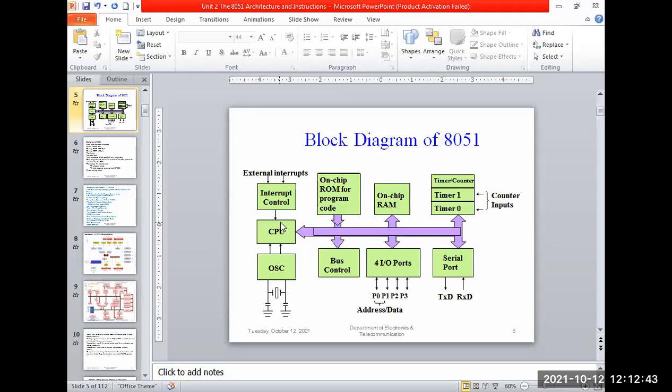What else? Starting with that, what are the other things there? If we talk about starting from this point, it can support the different types of interrupts, such as the hardware interrupts as well as the software interrupts. Okay, so it has the two hardware interrupts, that is called the INT0, INT1. Okay, and other total 6 are there.